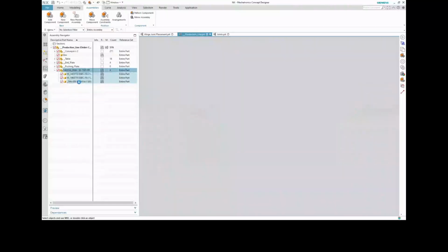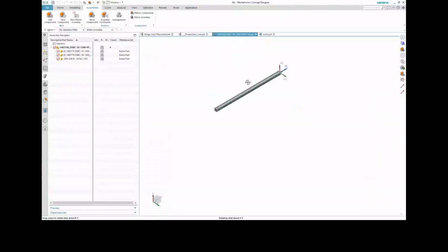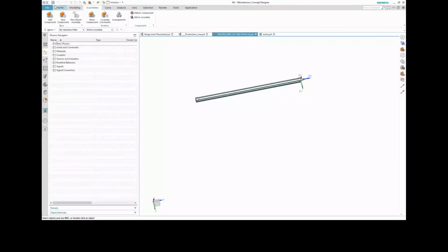And if I copy paste these objects so many times, all of that physics would appear so many times. Okay, so let's create a sliding joint very quickly. So my attachment is this. My axis vector would be this, and I say okay.